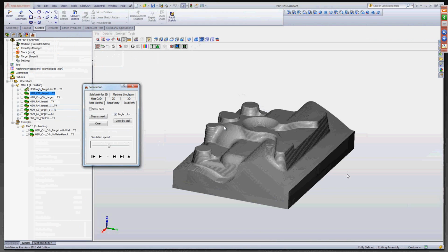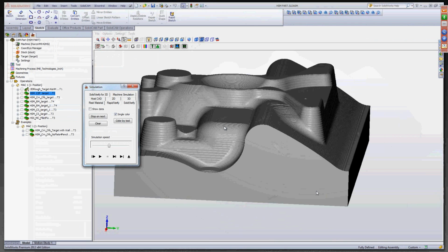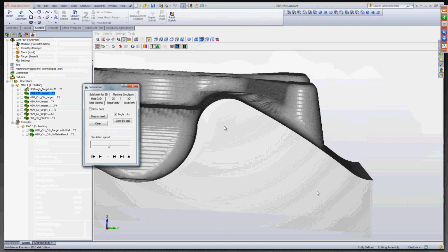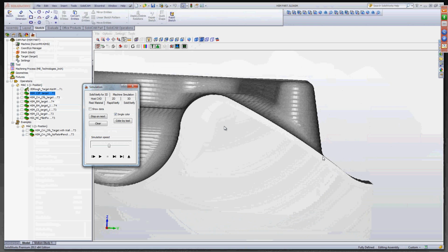You can kind of see when you look at it from this angle, it looks like, yeah, this is much more coarse here than this is here. But when you roll this over and look at it from the side, look at how interesting that becomes. The actual angle or the actual distance of the step here is the same as the scallop height here. From the very valley of the cut to the very peak of the cut is identical.